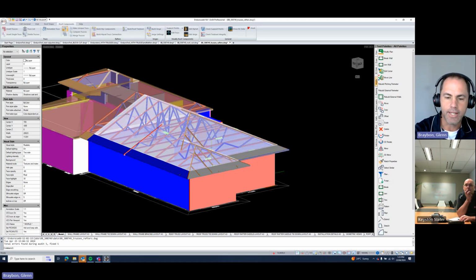So what we've done in the Enduro CAD is, did you understand why that error was coming up? Not particularly, because I looked at the NC data, sorry, and it was basically where it should be an end rivet flange. It was just an INS notch flange, I think? Sorry. Yeah, intermediate notch. INS. So it was an INS punch. The INS punch is the web punch, and that INS punch was after the end, or the E code, of the part. So you can't have a negative punch or a punch after the E code. Yeah. That's going to obviously cause drama.